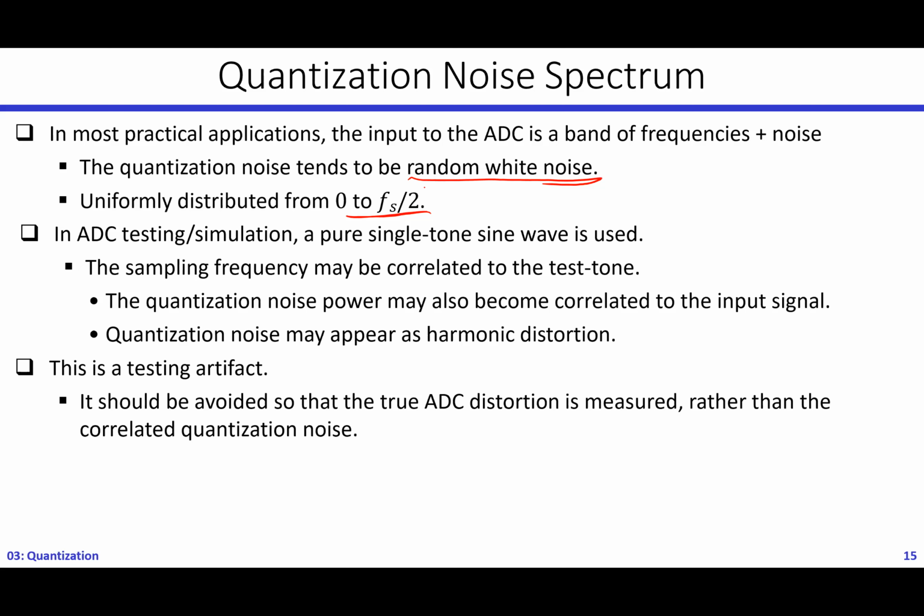Why is that? Because you know that the sinusoidal has a one tone frequency at minus F0 and F0, but we look at just the positive side of the spectrum. So it has a single tone frequency, and then you will see multiple things at the output. Those things that you will see at the output will be able to tell you how good your ADC design was, what the errors are, and how you should fix them. That comes with time and experience.